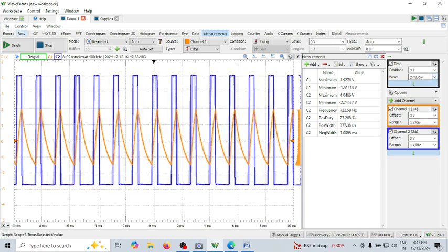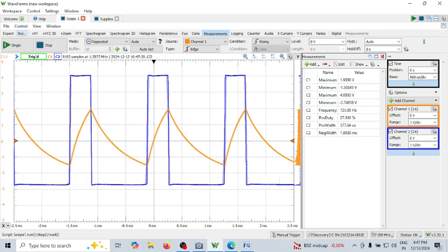Let me further make it maybe 500 microsecond. It is interesting to see now. So let me run. See now the duty cycle has reduced to 27%. The duty cycle has now gone away from that 40%. Now it has become 27%. So now again, this is for an RT on of 3.3 kilo ohms. So this is for a 3.3 kilo ohm resistance.